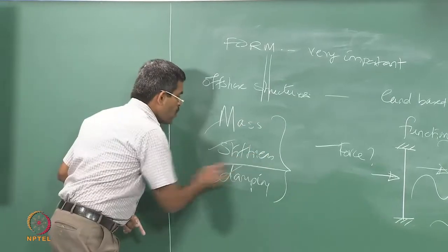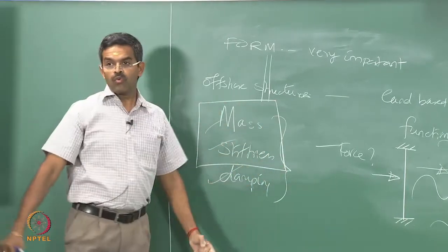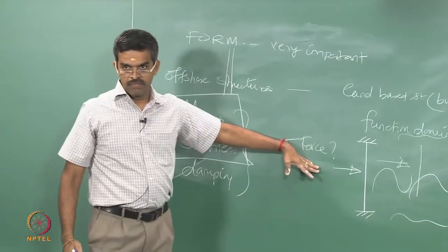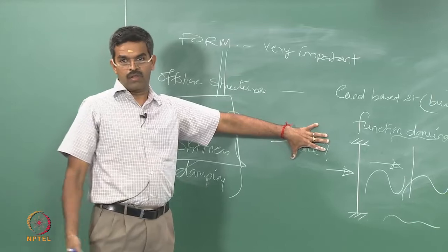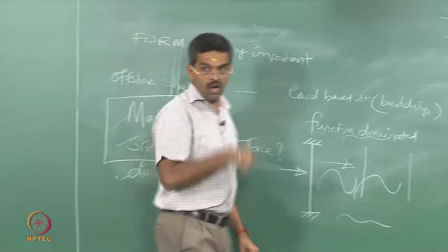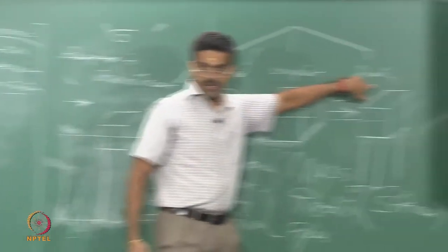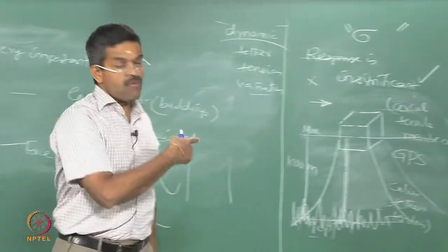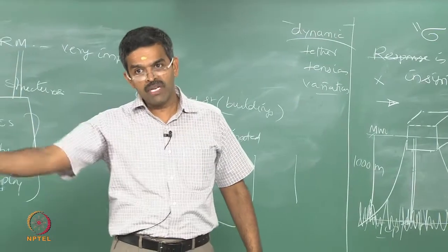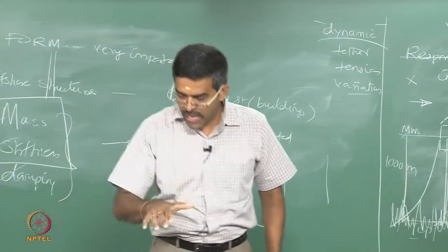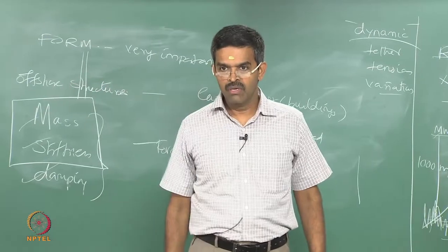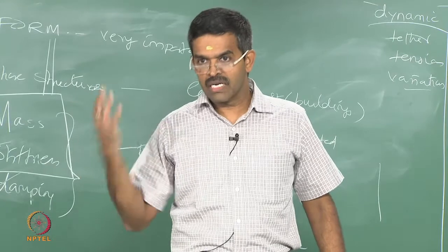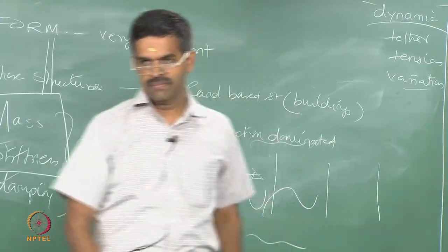Now, the question comes, why amongst these 4 these 2 are very important, why these 2 are not important? Because if there is no force, one can say the structure will not move, but the structure is meant not to move because it is freely floating. This is one of the important characteristics of any offshore platform, because this will save a lot of time and money in terms of commissioning the platform. The platform should be able to free float on its own. The day you make the platform float on its own, erection and commissioning charges will drastically come down.